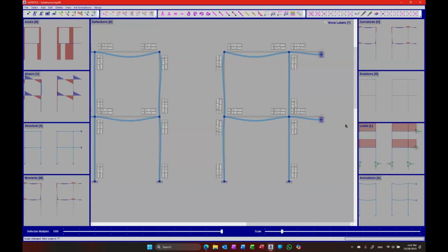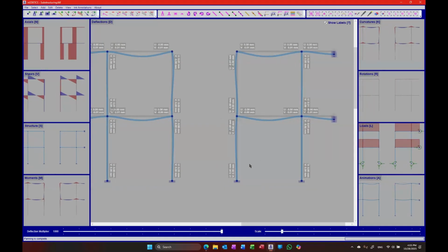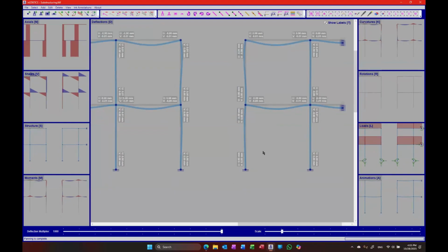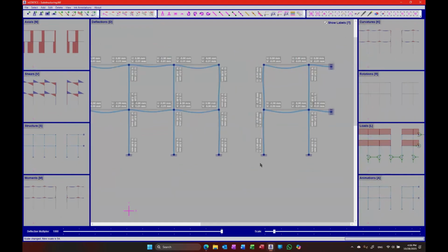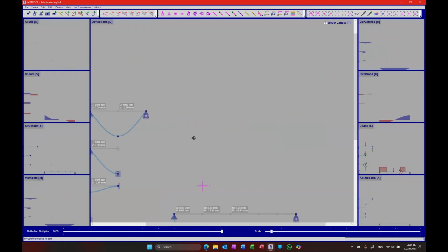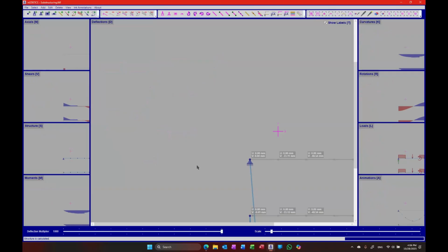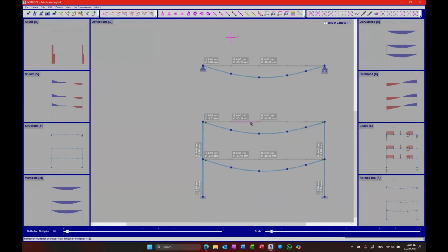There are other ways where you can simulate point symmetries, not just line symmetry like this or plane symmetry like this. I'm not going to get into those, but I just want to show you that there is something called substructuring that people use on a regular basis, or used to use on a regular basis to simulate really large models. They still use them very often in SolidWorks, etc., when they're modeling,